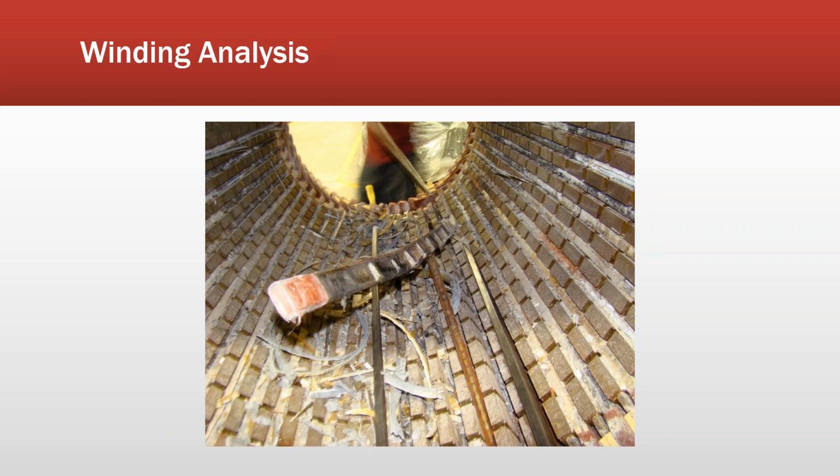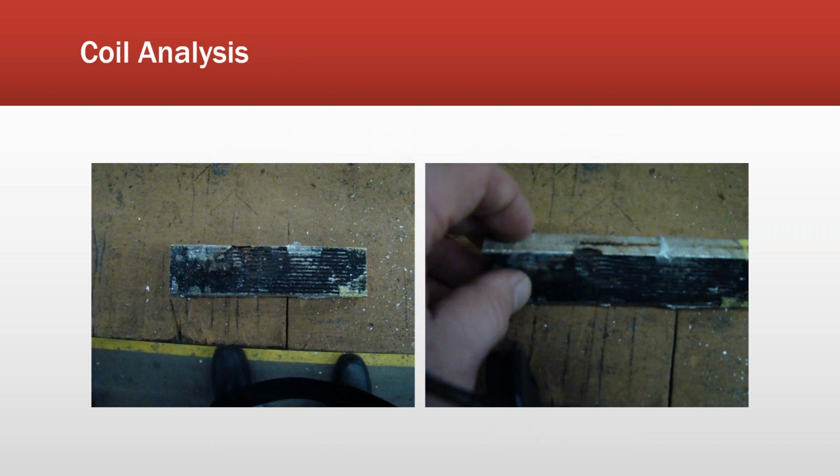And then those would disintegrate in between the stator and the rotor and worm their way into the winding and cause the failure. Now, what's really kind of cool is that's the number of stator slots times the RPM plus and minus the line frequency. That's the signature. If we see that signature, then we know we have that kind of issue. We can tell how severe it is because we know that a short's going to start to occur between conductors. This is after we took the layers off. This is the actual conductors and where one failed.